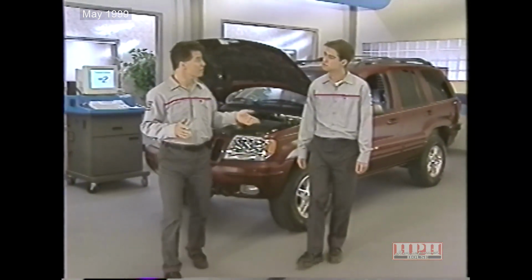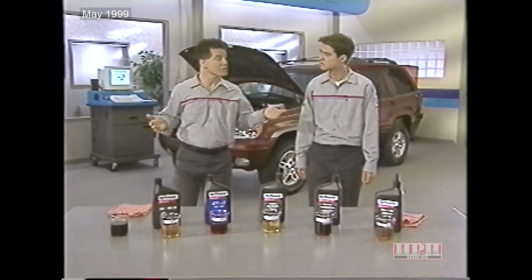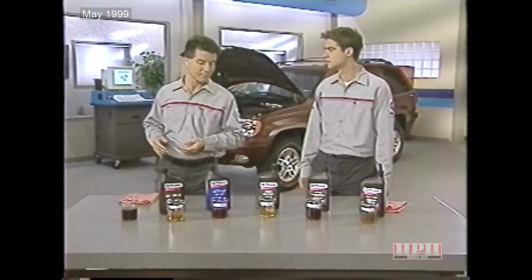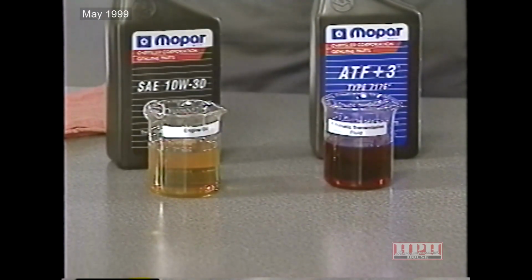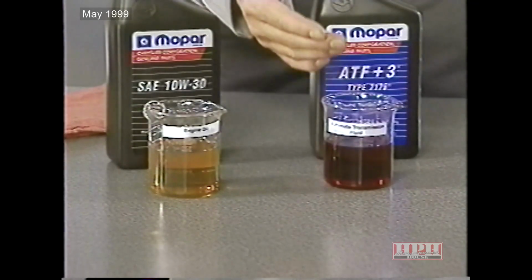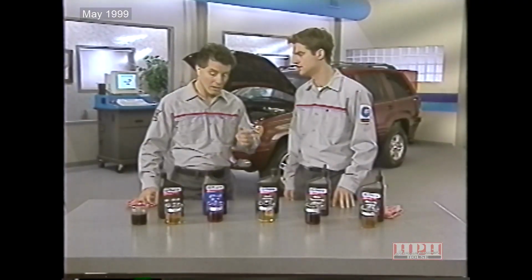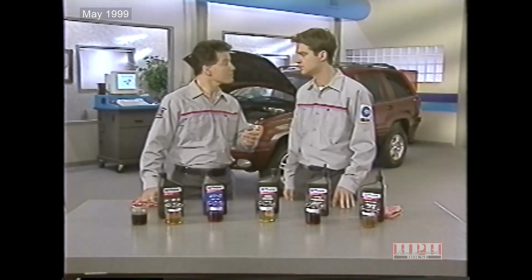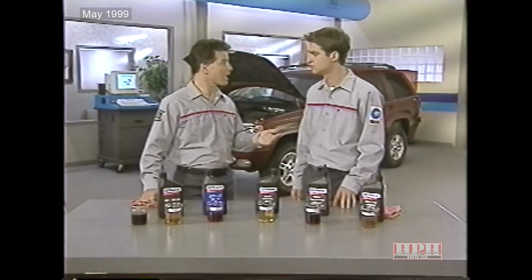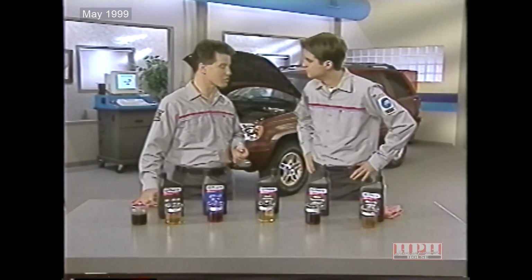Sometimes you can identify the fluid that's leaking by its color. But remember that you can't always depend on it as a positive ID. For example, the engine oil is usually amber or black, while automatic transmission fluid is red or brownish red. Well, why can't we depend on color comparison? Well, for two reasons. First, some fluids can become discolored with age and vehicle mileage, making it hard to determine what their original color was.